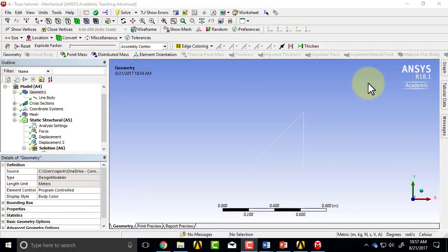At this point, we have completely defined the mathematical model in ANSYS, and ANSYS knows how to relate the pin displacements to the potential energy. So it can solve the mathematical model by writing the algebraic equations that relate neighboring nodal displacements. And as we saw, this comes from minimization of the total potential energy. Let's get ANSYS to solve the mathematical model.